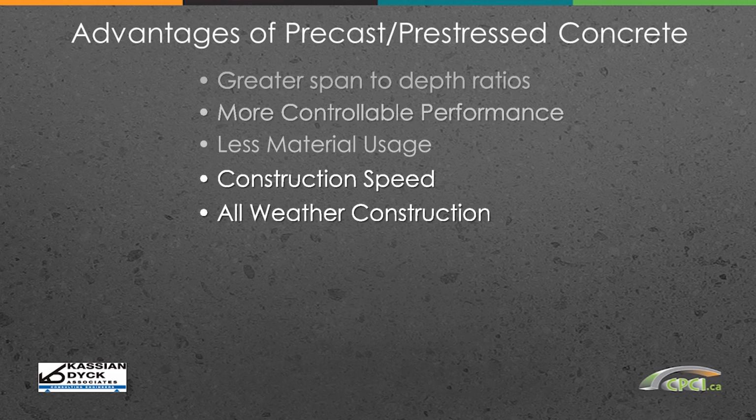You can begin casting components for the superstructure off-site while foundation work is in progress, leading to an accelerated construction schedule. You also get the benefits of construction speed due to precast concrete's ability to erect the superstructure quickly all year round, so the project can avoid delays due to waiting for concrete to cure on site or delays caused by harsh weather.